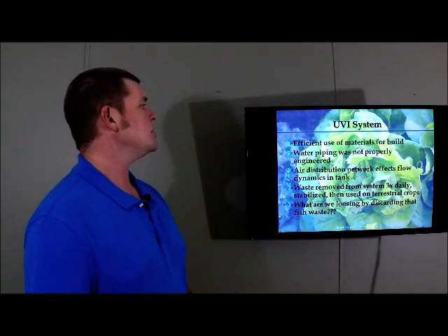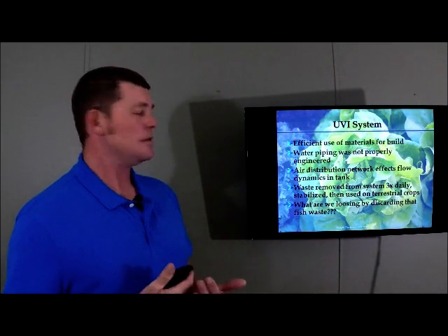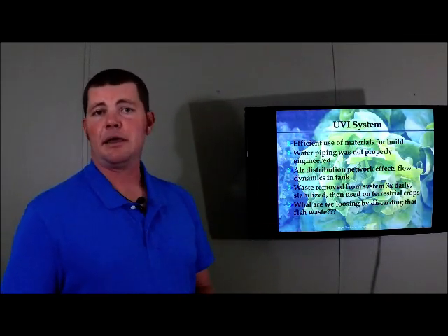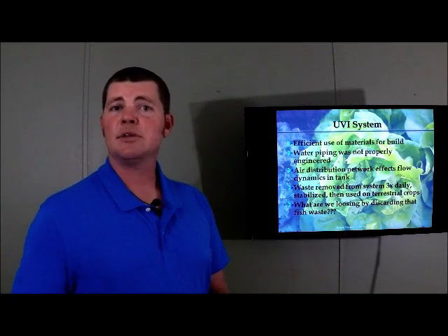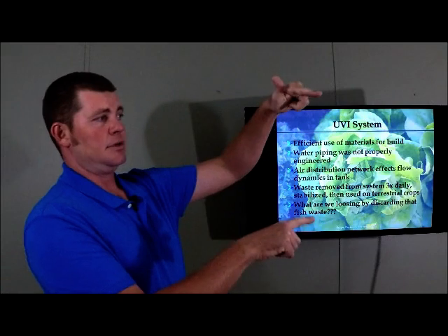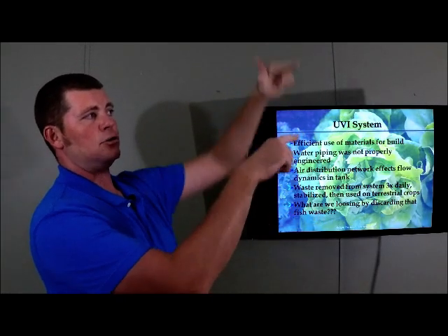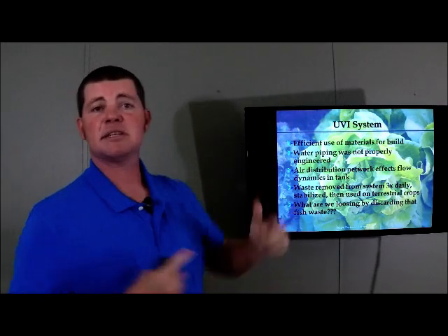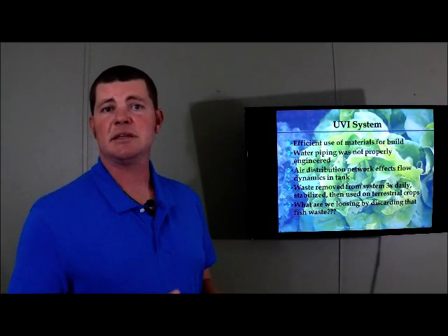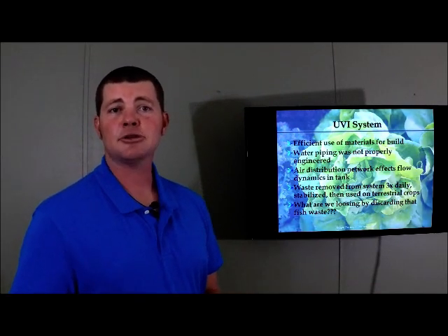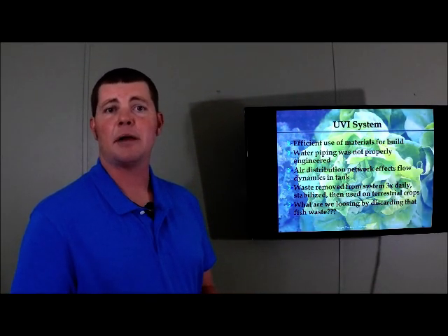The air distribution network in the fish culture tank affects the flow in the tank. The air stones are placed around the entire rim of the tank and dropped vertically. So instead of a long rectangular stone, they're dropped vertically into the tank and hung. Well, first off, that messes up any kind of flow dynamics within the tank. That disrupts our tangential and radial flows that are going to naturally drive the solids to a center bottom drain.